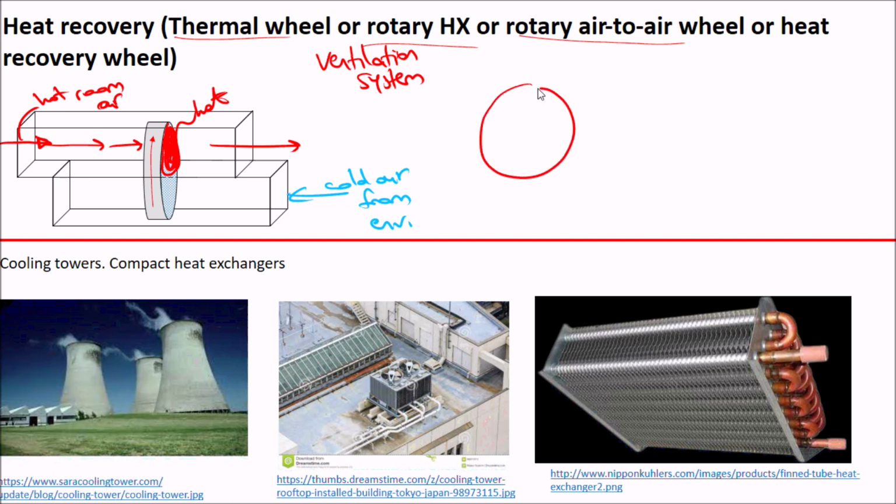So I show the cross-sectional view of this heat exchanger, and there are fins here, lots of heat exchanger fins here. Okay, so these fins are also called the matrix. Because here you have gases on both sides, they help to increase heat transfer, as we have talked about in our first slides. Okay, so then this part becomes very hot.